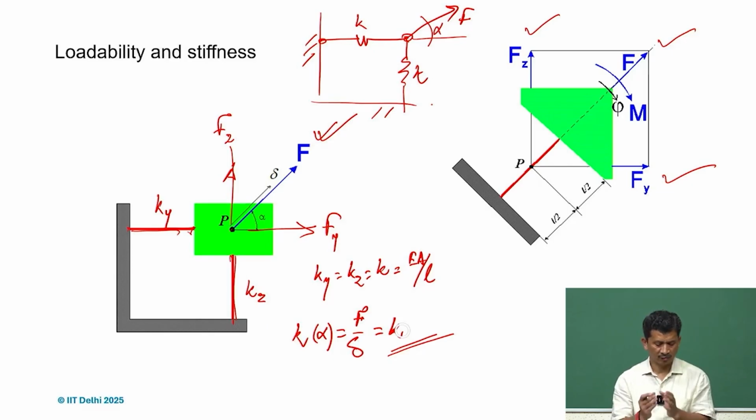So it's a very good example of the same radial stiffness, just by putting two orthogonal stiffnesses, and we can feel the same stiffness in any direction. Now, if we remember what we discussed during controlling degrees of freedom, these are two constraints.